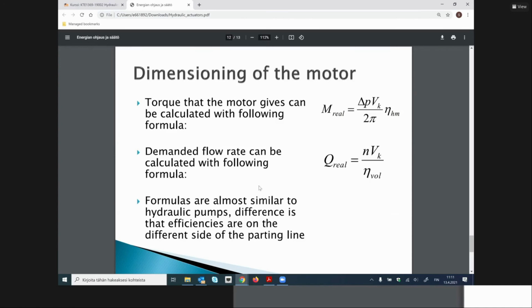Simo, but what are applications for hydraulic motors? I mean, it's probably very hard to control speeds and to adjust speed with the hydraulic motors. So not so hard. They are very common in mobile machinery propulsion. So there can be so-called hydrostatic transmissions. For example, an agricultural tractor, when you drive with that one in a forest, or an excavator, there are hydraulic motors to spin the wheels.